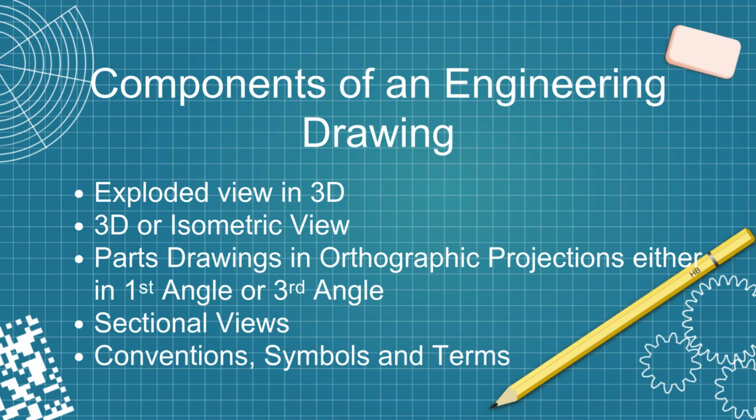The key components you will typically find are an exploded view in 3D, a 3D or isometric view, parts drawings in orthographic projections either in first angle or third angle, sectional views, and conventions, symbols and terms.